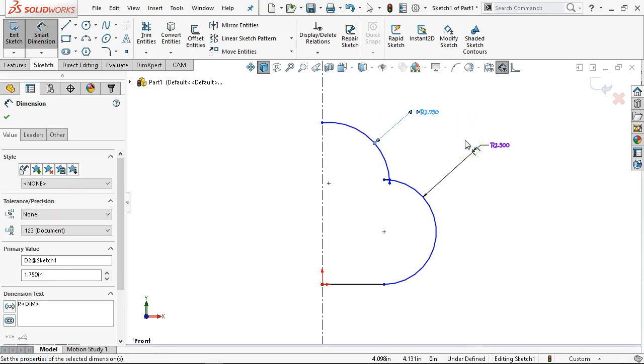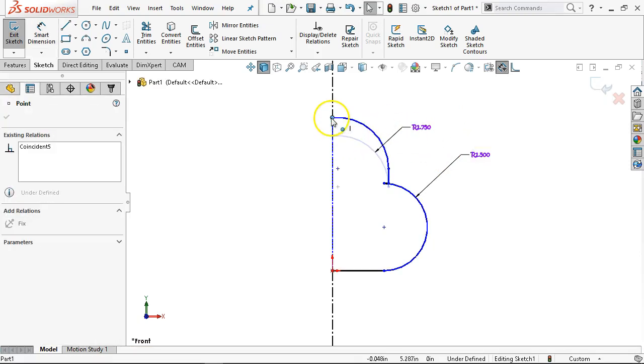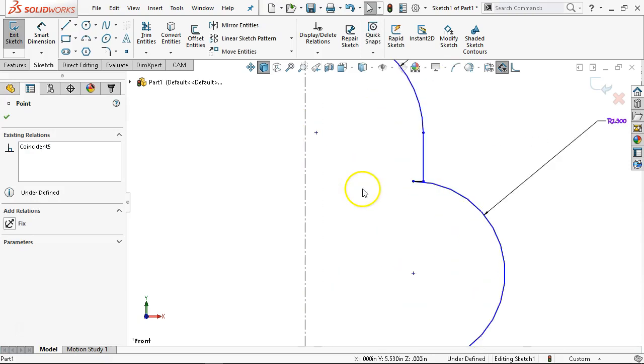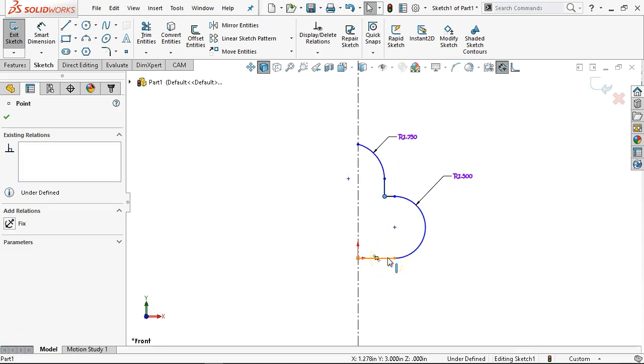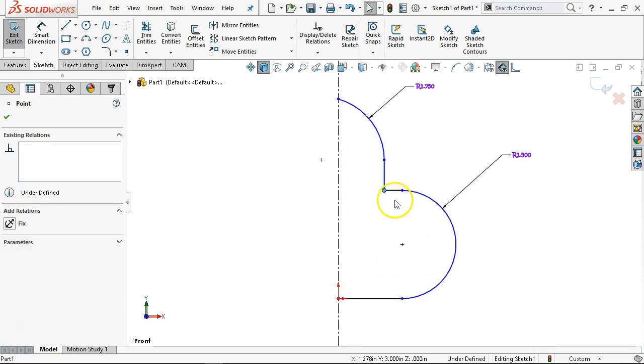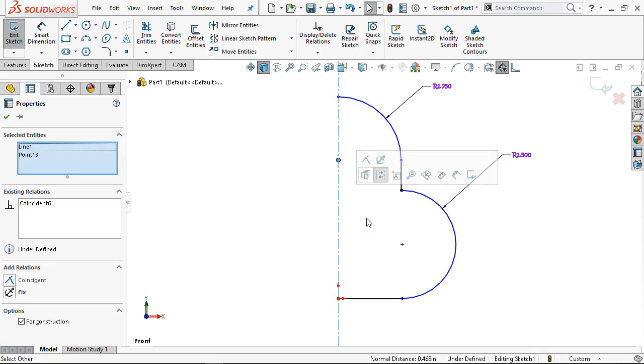All right, so there's a little bit of inversion going on that jumped on me, and I'm just going to grab an endpoint and drag something up, zoom in, drag something over, and put it back the way that I expected it to be. It's not a big deal that it can do those things. The problem is recognizing that if I pull this way and stretch this way, that will get it back to the desired result. So my center point, and control select the center line, make those coincident. That's going to give me a 90-degree arc.